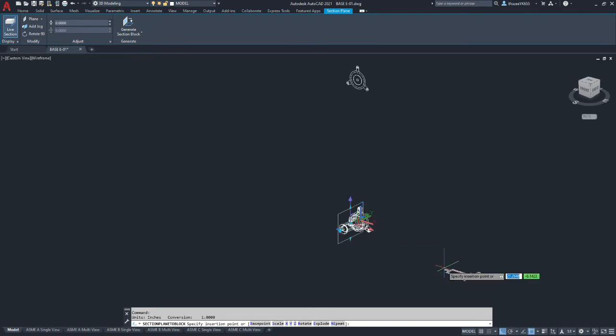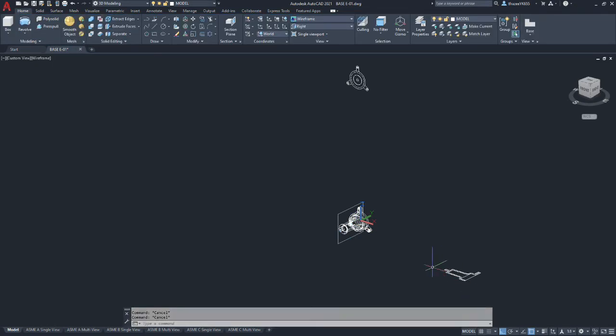And then we'll place our view pretty far away. We go 1, 1, and 0 on rotation. Because we do want it oriented with this on the right facing, with the pen facing our front view so that we're using the horizontal paper space for our drawing.